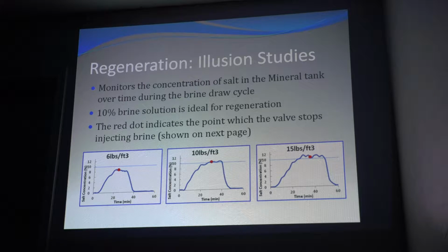So, what does that mean? Well, that means I've got 40 minutes of draw that typically is just slow rinse. If your brine tank is full of water, you're going to draw it all out eventually. Through that first cycle, you might have a little bit of salty water, but that's where your fast rinse comes into play. It'll purge that because you're going to turn that over quickly. You're going to have just a super regeneration ultimately, because you're going to draw to concentration and it's going to flatline right at the top because you're going to have such concentrated salt all the way through the brine draw.